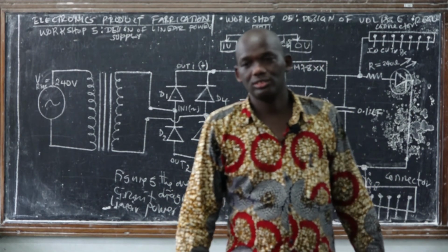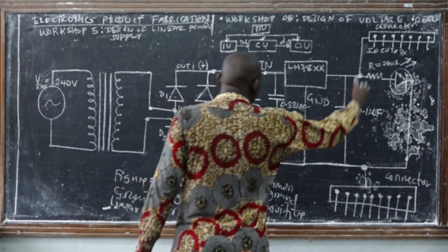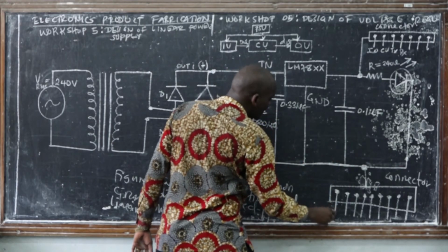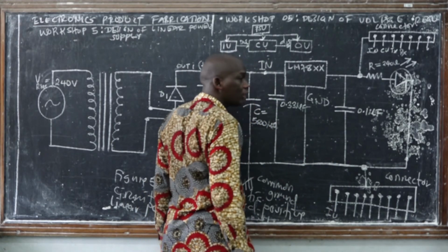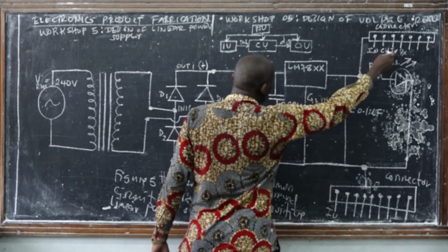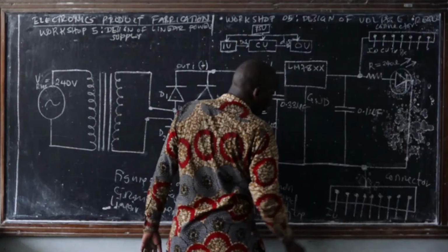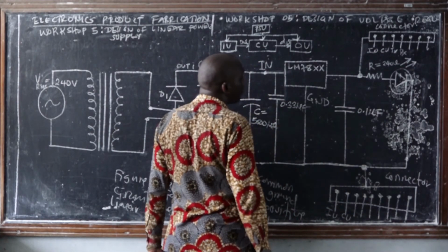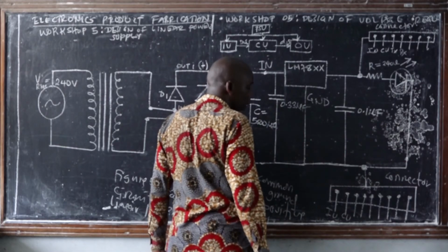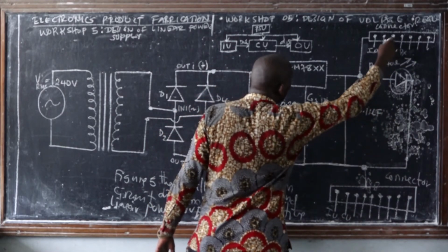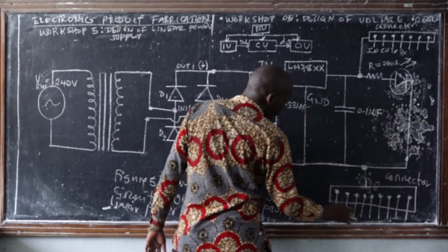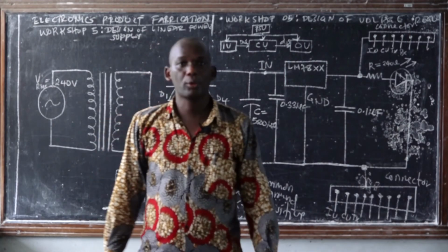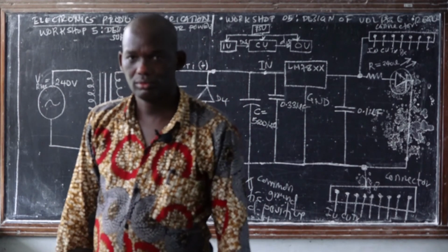Yes. Good. So similarly, if we take this input supply or the power to the input unit, we also need to take its corresponding ground terminal. Again, if you use this terminal to provide the positive power to the control unit, then here we are going to have the control unit connected to the common ground. If again here we have a positive power fed to the transmitter, you also need the common ground to be fed to the transmitter. So that's the process.